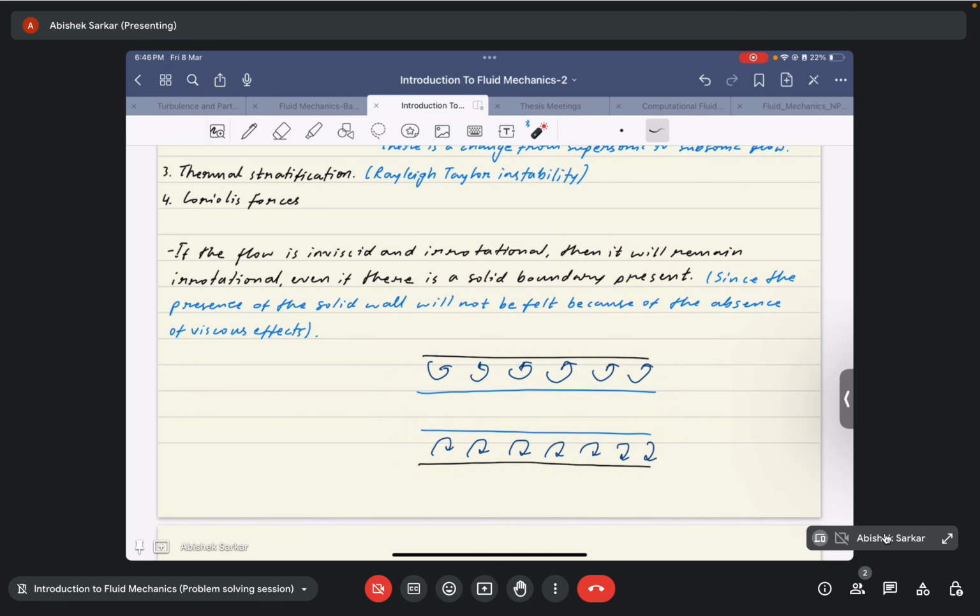That essentially will not generate vorticity, but may induce some kind of flows that may create vorticity. Just to be safe, I'm leaving the upper surface and going just below it and above the river bed. That region can essentially be considered inviscid. Not zero viscosity, but inviscid, because it is far away from all the edges and all the vorticity generators.